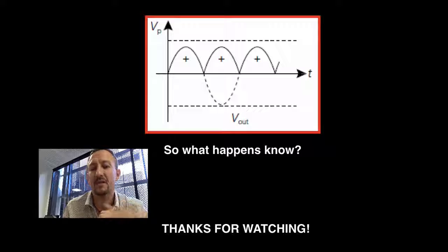They're all on the same side of the curve, which is great, but it's like turning and switching the lights on and off and on and off and on and off. It's not good for the circuit. So somehow we've got to produce a flat line curve, a horizontal flat line curve, where we fill in those gaps between each of those positives. And that will come down to capacitor smoothing, which I'll introduce in the next video.